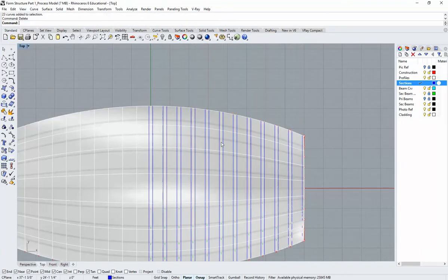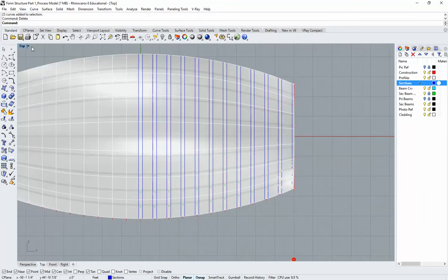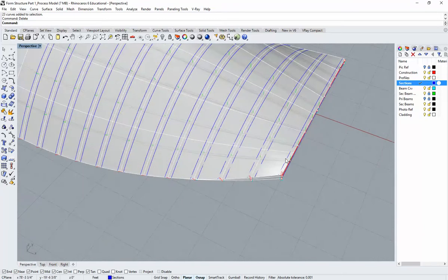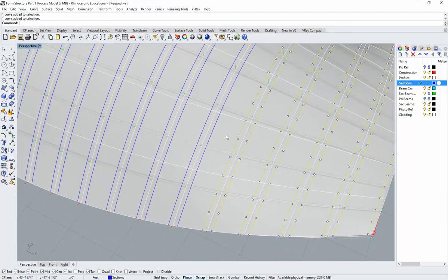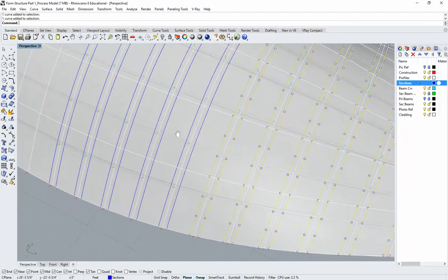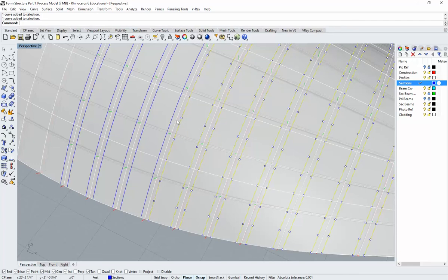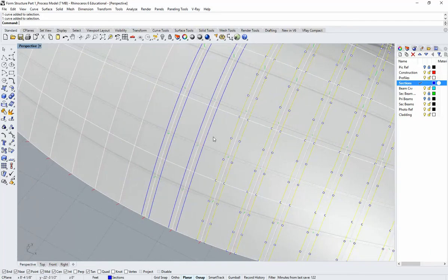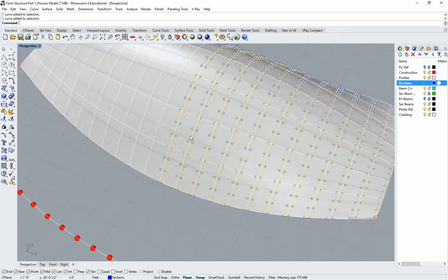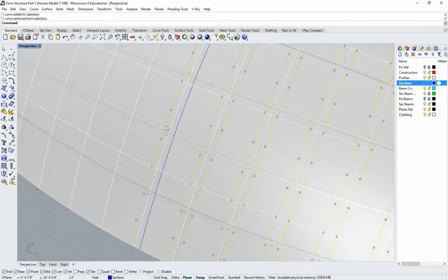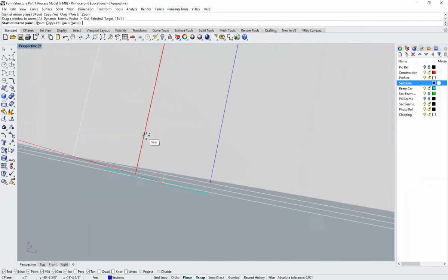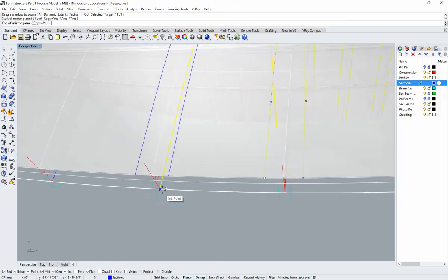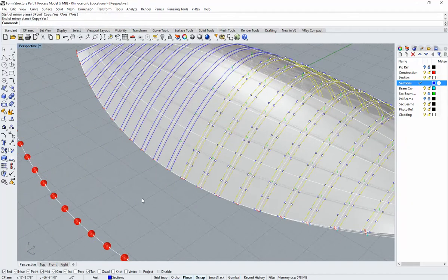We don't need those construction lines. I'm going to delete those because they get kind of distracting. I'm going to head back into this view and select sections and just mirror them around. And I'll have my completed cage. And I don't need this necessarily to model all those 3D sections, because I can get rid of those, because I can mirror it around. But I like it because, again, if I wanted to do a drawing of the entire cage as a wireframe, as a continuous wireframe of the entire structure, I would then have those lines ready to go.